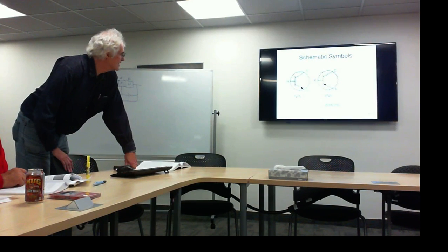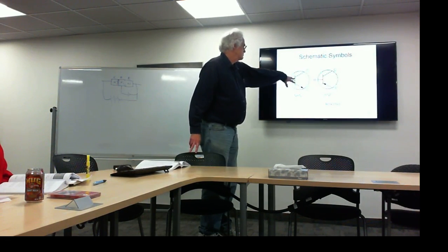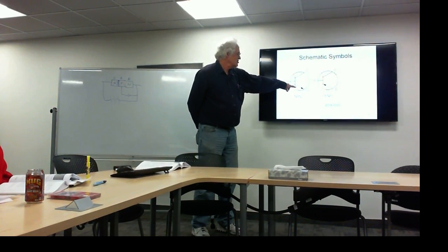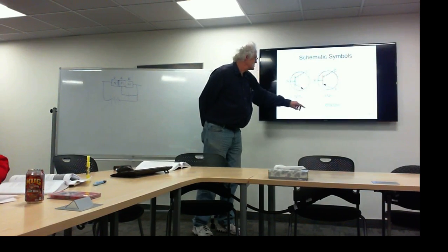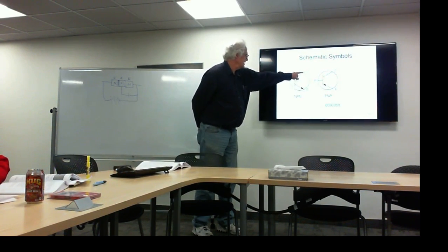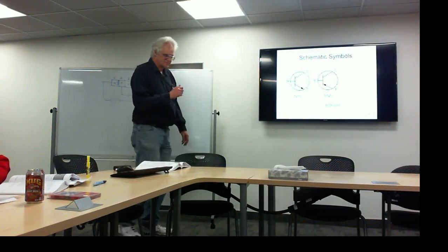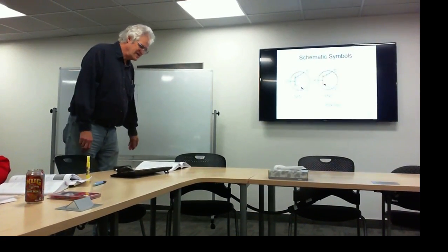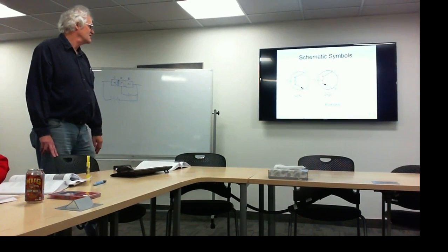And again, this will probably be a pretty good question near the end of the test. Those are your schematic symbols. The arrow is always in the emitter lead, with the arrow always pointing from P to N. P to N, so therefore we have NPN, and likewise we have a PNP transistor. So the arrow points from P to N, you said always? The arrow always points from P to N, just like in our diode example. That's always, always, always.